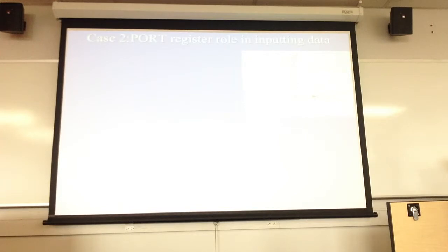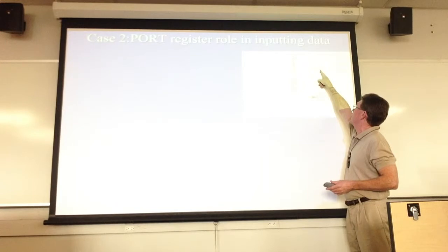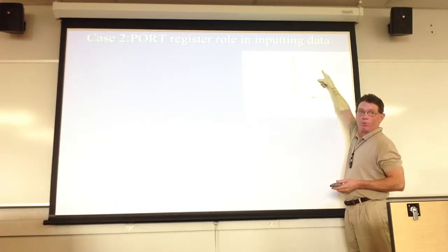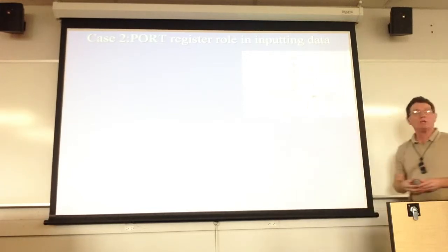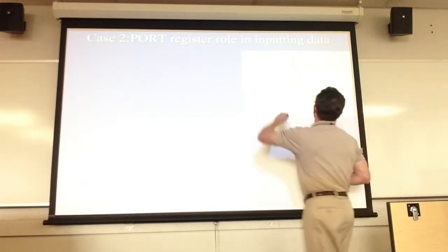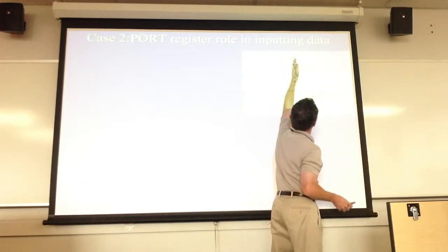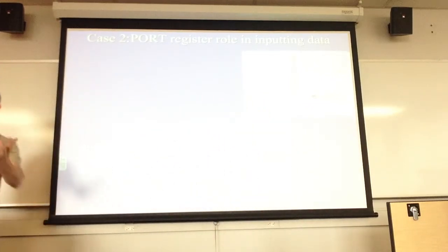All right, and so what you have here is port, whatever port I'm working on, C or B, and whatever pin I'm working on. That's what X stands for, the port you're working on, and N is the actual pin number. So each one of the pins has a pull-up resistor sitting in there. What effectively you can do is control this pull-up. We typically always set that. So when I'm reading something in, always set up those pull-up resistors.